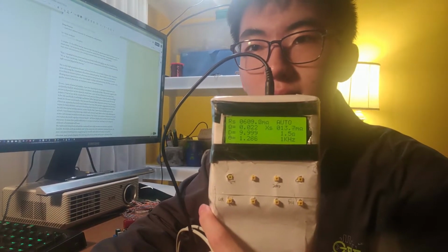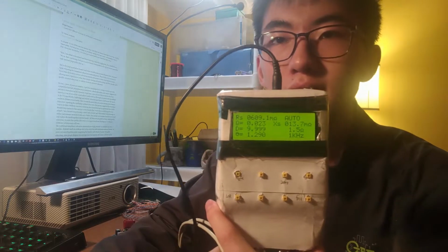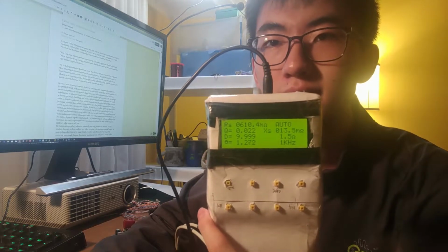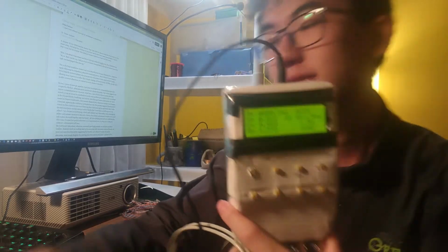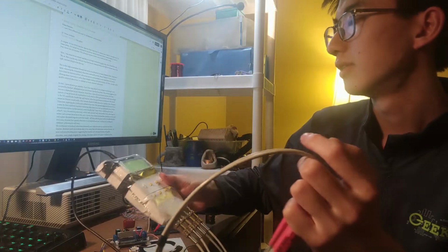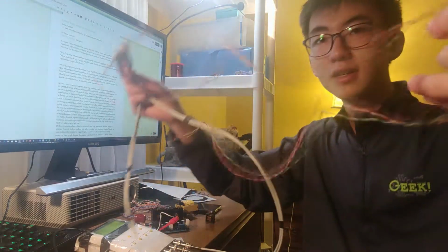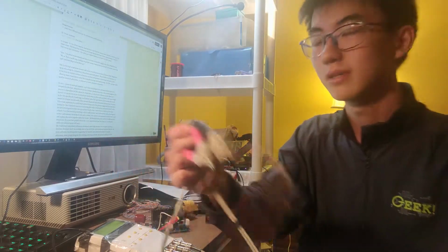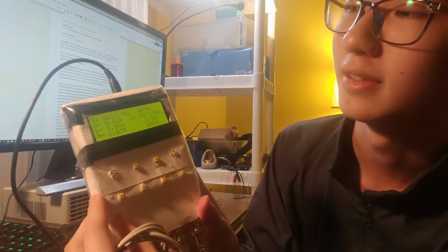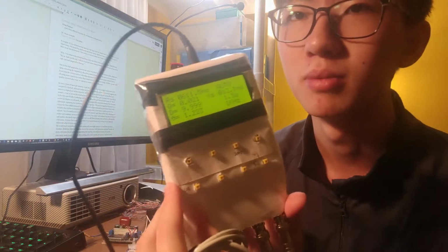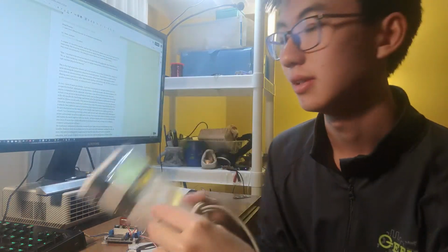Here I have an LCR meter to further explain electromagnetism. What it does is analyze the properties of a component, essentially. Right now it's hooked up only to a piece of wire, as you can see here. It's just wire, nothing too special going on. Right now the reading is 614 milliohms, which is a resistance. It has very minimal inductance.